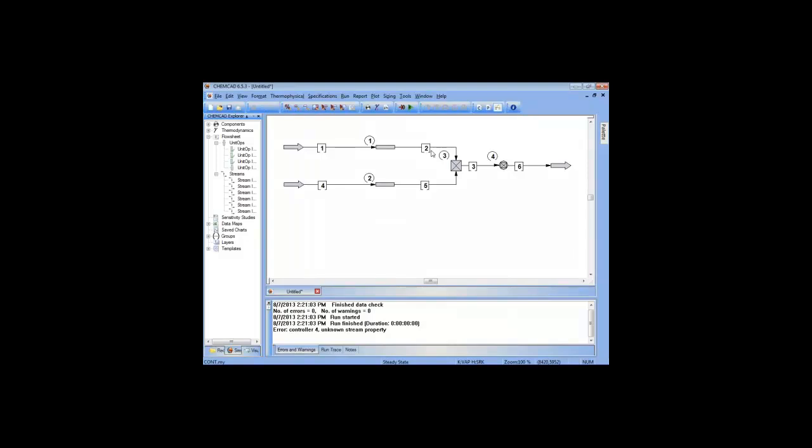Okay, so what this is telling us is that because these two pressures do not balance, we either have incorrect flows on one of these two streams, or we have incorrect starting pressures on one of these two streams. We don't necessarily know which. But we know if both of them are at 50 pounds and both of them are at 500 gallons per minute, this is not what will come out.